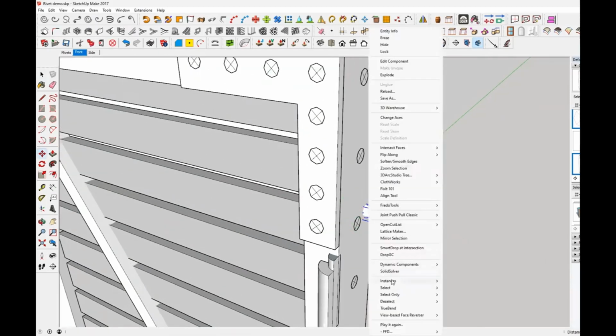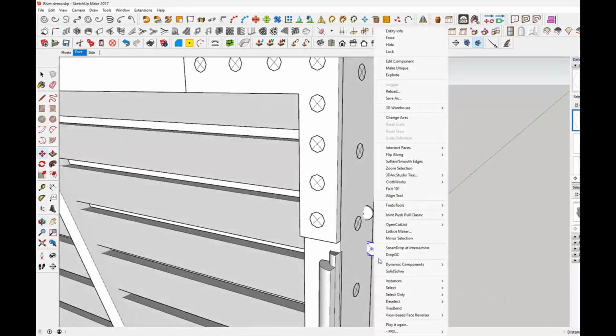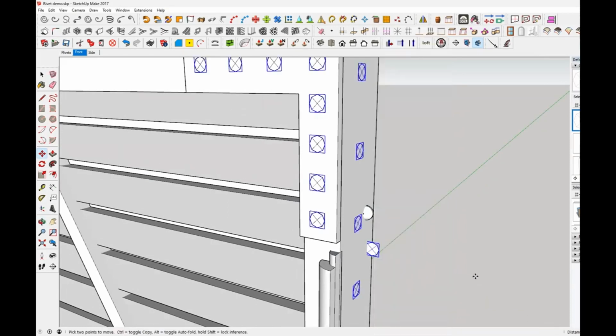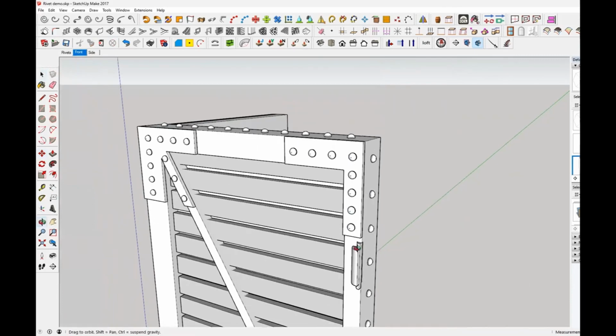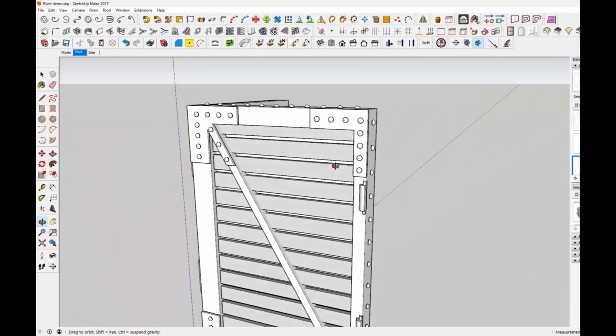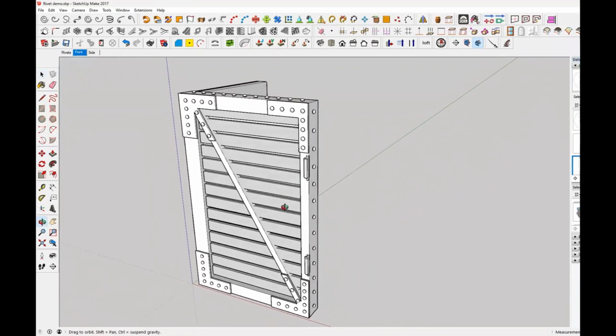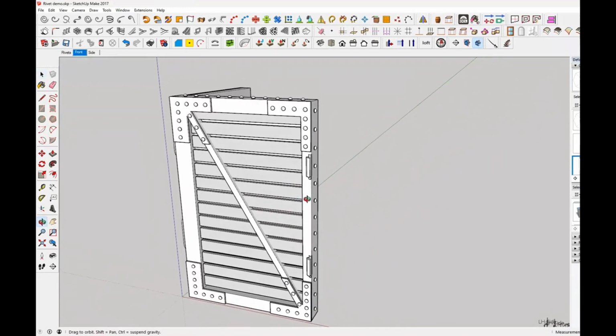We'll right click, we'll select, actually no, we want to click on our rivet replacement. We'll right click, instances, select all, and then we'll right click on the rivet and replace selected, and then we go, we've changed our template type rivets back to normal rivets. So it's a good way of cutting the size down and move them around easier.